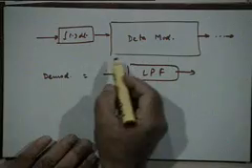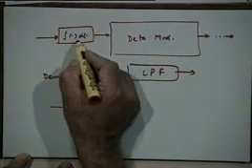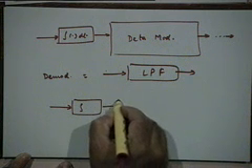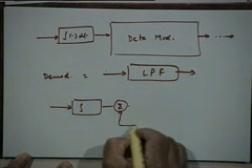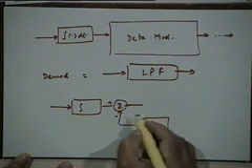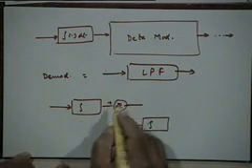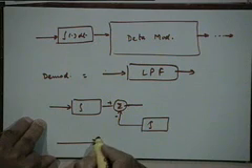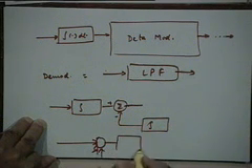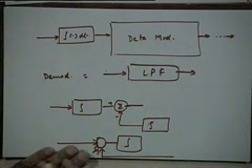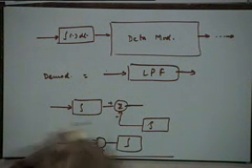Also, you can simplify this itself. If you think about it, this integrator may not be outside this plane. In fact, you see there are two integrators, one is here and the other one is here, right, and we are just adding things here. I can remove this here and, in lieu of these two integrators, I simply have one integrator here, right, that takes care of both the things. So, my feedback path is simply a straight line. So, my final diagram of the sigma delta modulator becomes,